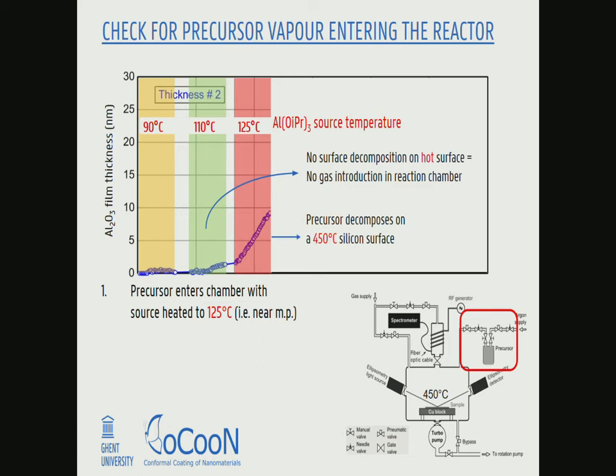This is not ALD, but this is the first step, you could say, towards ALD, because you have actually verified that some molecules are reaching your heated substrate. Now to go into ALD, you're at much too high substrate temperature, so once you have determined this, you can fix this temperature, because now you know what to do to get a vapor into your chamber.